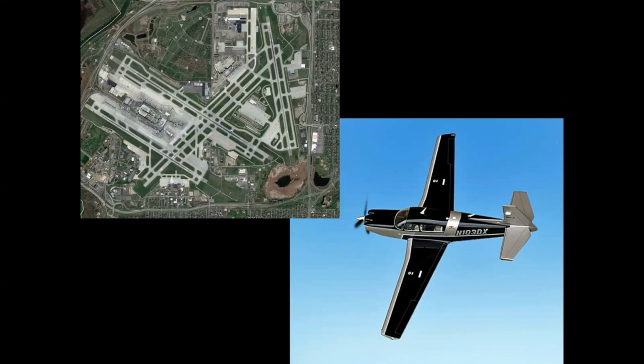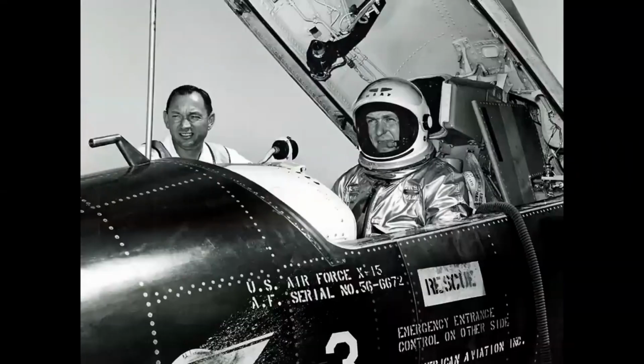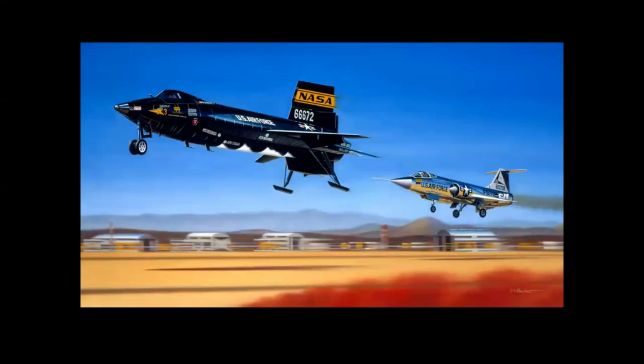Types of drawings. Drawings must give information such as size and shape of the object and all its parts, specifications for material to be used, how the material is to be finished, how the parts are to be assembled, and any other information essential to making and assembling the object. Drawings may be divided into 3 classes: detail, assembly, and installation.